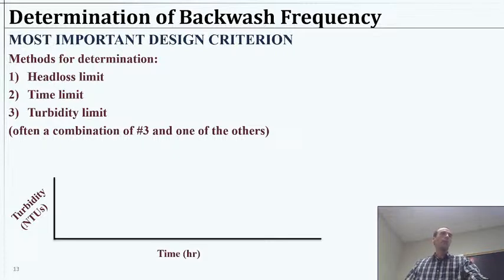Typically, this could be anywhere from every day to every 2 to 3 days, maybe even 4 days. We'll have some sort of a cycle, and the cycle will essentially consist of a few parts. First, this ripening. We give it time to clear out any of the bad particles that were there in the previous cycle we just backwashed. So we'll start by that ripening. That'll be kind of our cycle start. And then we will go on and do our filtration for some time, and then we'll backwash.